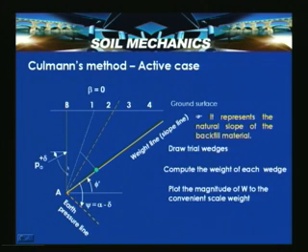Similarly, once you have drawn AB1 as the wedge, determine the weight of this wedge per meter length. Gamma is known to you, so you calculate the weight, and that weight is plotted on a suitable scale on the weight line or slope line. So, AB1 weight is indicated as, say, some point A dash.